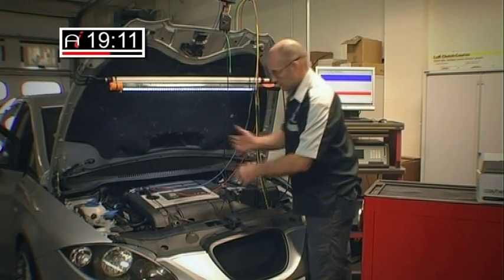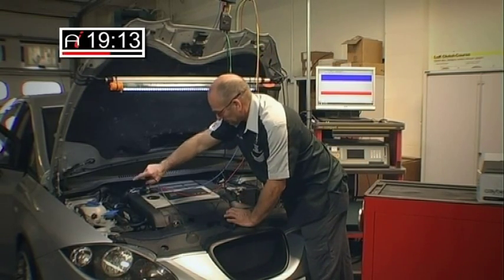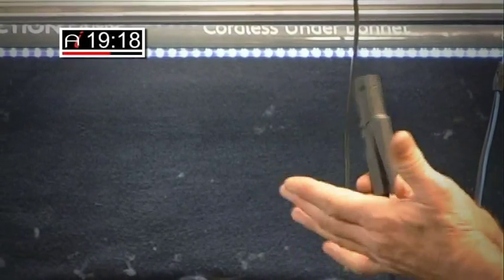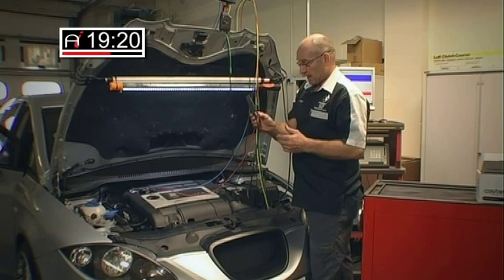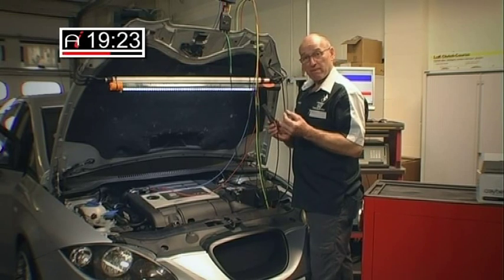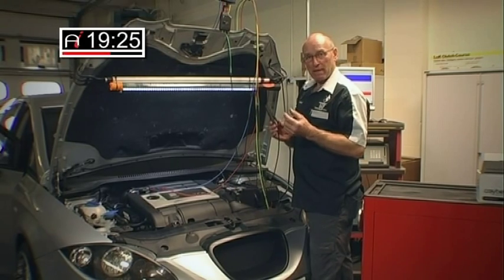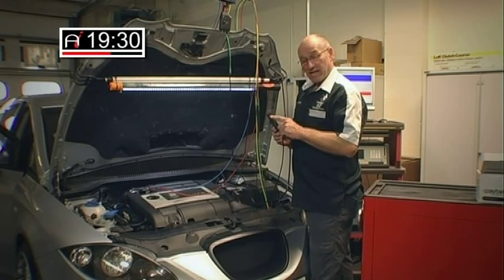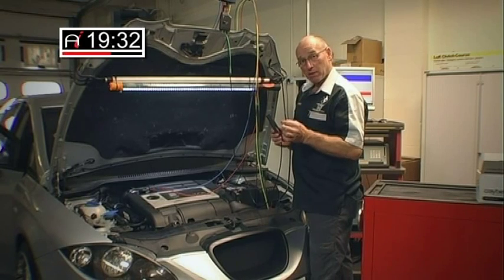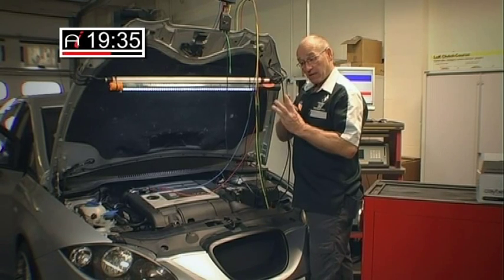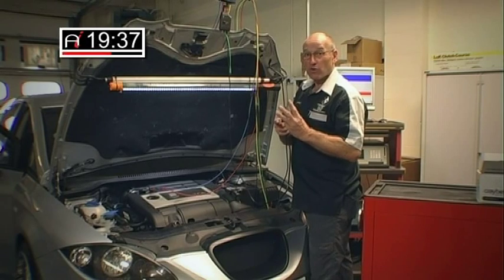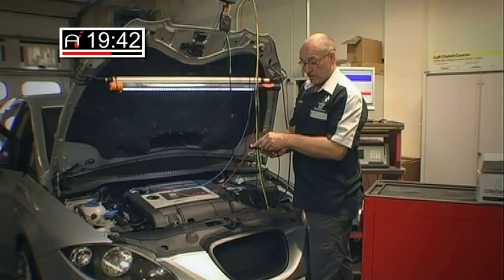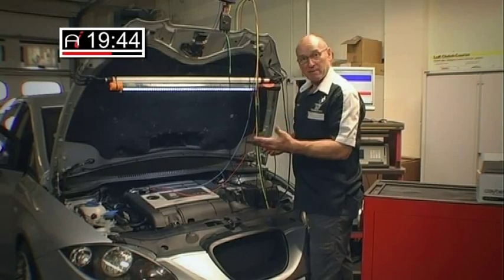The device connects by means of induction, and its sensitivity is such that it can accurately measure very low amounts of current flow through a circuit. With the air mass meter, we attach this device to the power cable to the air mass meter. Remember, output, power, ground, all devices will have all three. The power lead to the air mass meter, with the arrow towards the device. The device is the air mass meter.